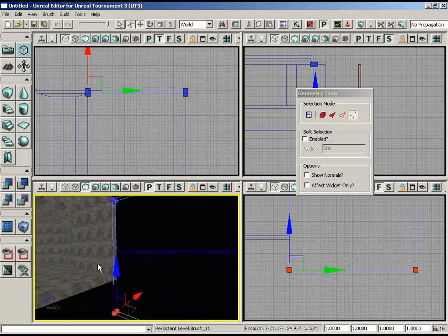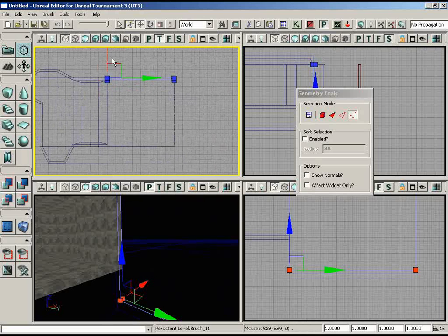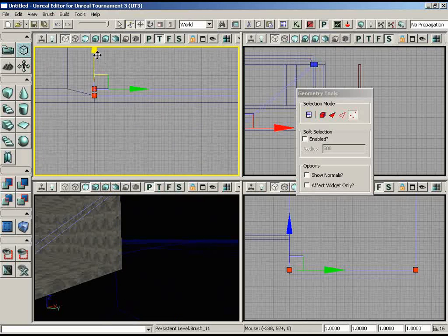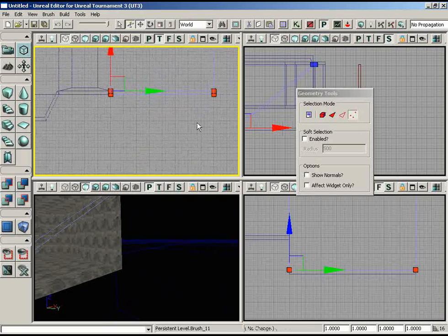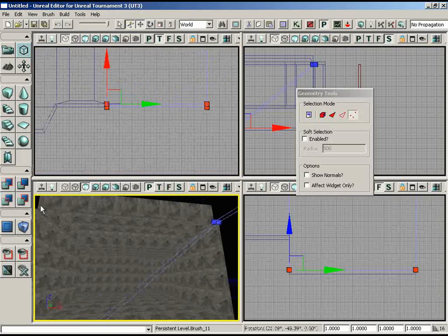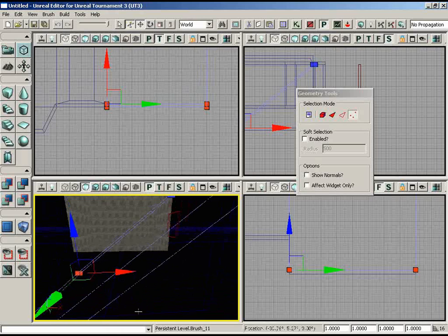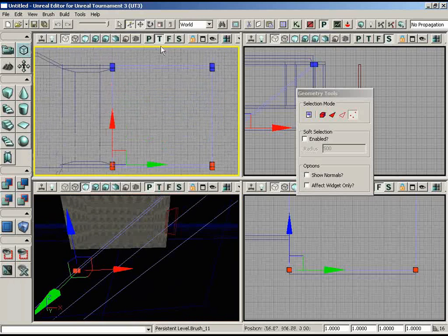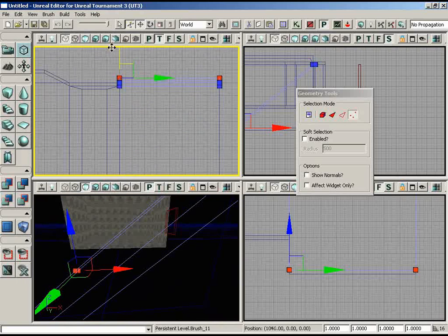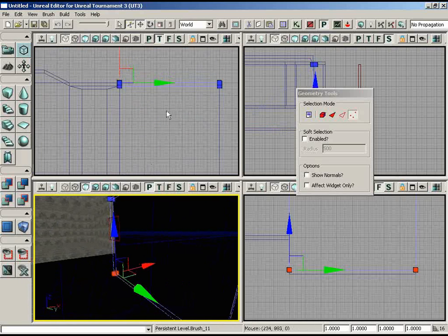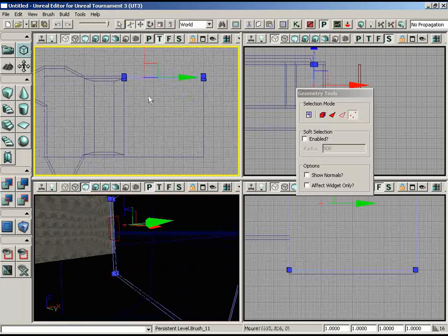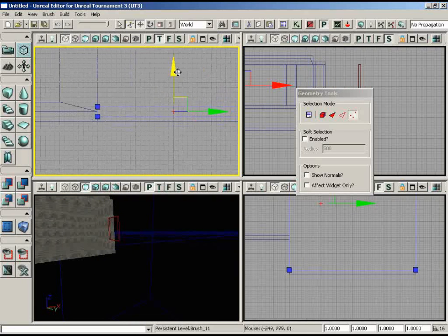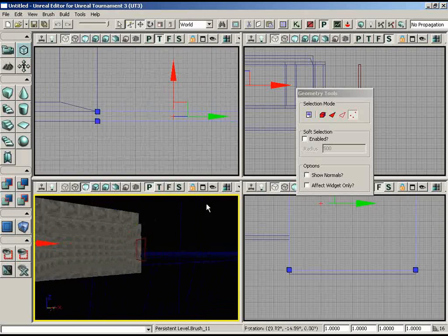It's looking good as far as dimensions, so let me duplicate it to the other side. Drag this over. Let me zoom in just a little bit so I can make sure that the... I'm not 100% sure that you had reselected. You might want to undo that. Oh, look what happened. Yeah, good eye on that. What had happened is, it seems I was in vertex selection mode, and I grabbed the bottom vertices only. So how about we put those right back where they were, and reselect the brush so we have the entire thing. Alt drag, and that way we're duplicating and not just dragging the bottom vertices. So there, now we have a brand new brush on the other side.